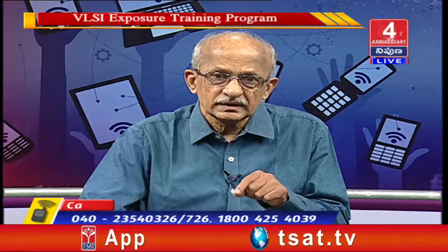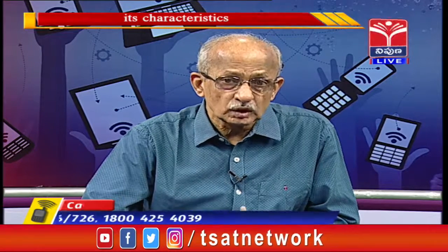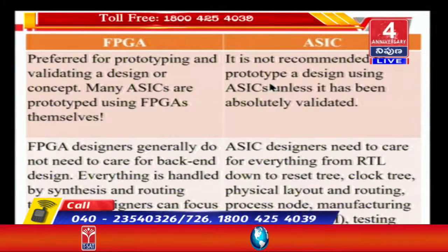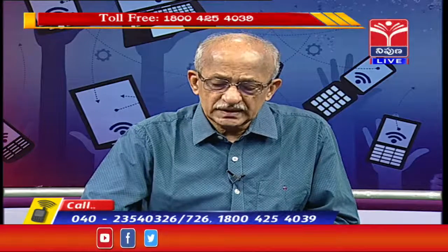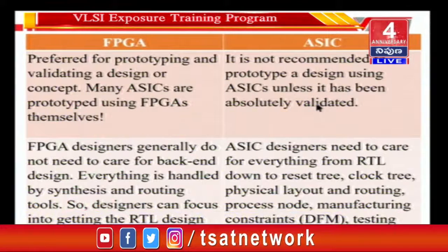Putting the design in an FPGA means that you are verifying this particular design in the FPGA. The ASIC design is getting implemented in the FPGA and is being verified there for its functionality. It may not work at the required speed, that's okay, but still the functionality is being verified in silicon. Whereas with an ASIC, you don't verify an ASIC by making an ASIC. It is not recommended to prototype a design using an ASIC unless it has been absolutely validated.